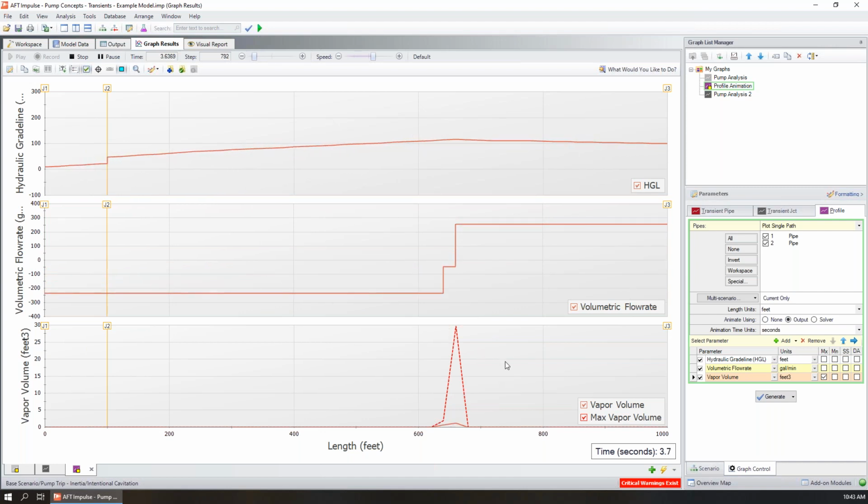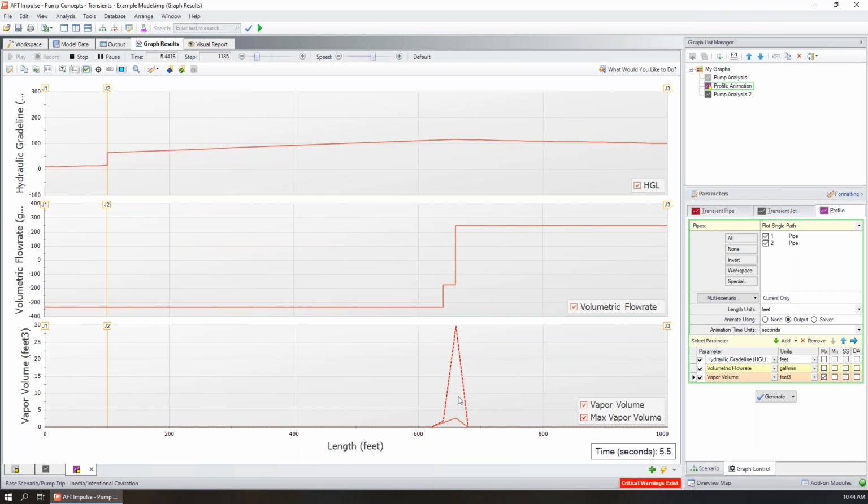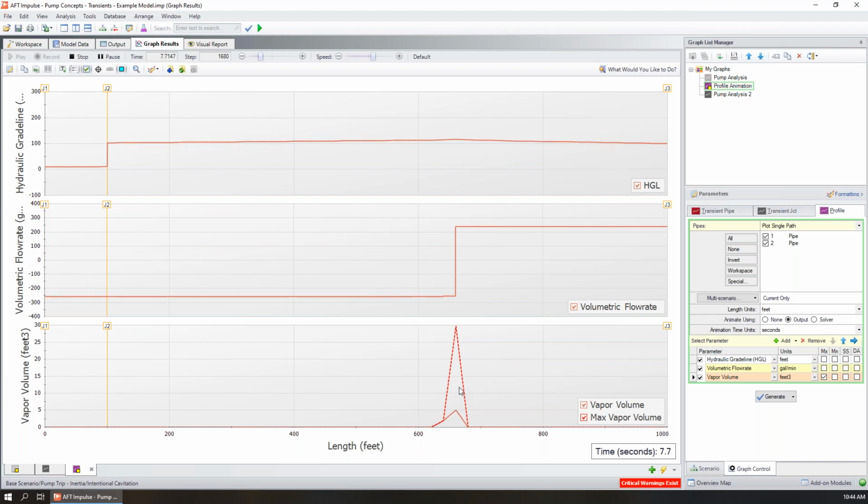So this isn't a sustainable operating point. In reality, what could happen is the vapor volume could continue to grow until it breaches a pipe and then kind of drains everything out. You can think of it like putting your finger on top of a straw, and that's why the liquid doesn't drain out, because you're creating a fixed pressure at the top where it wants to drain further, but the fluid could cavitate at that point, right?